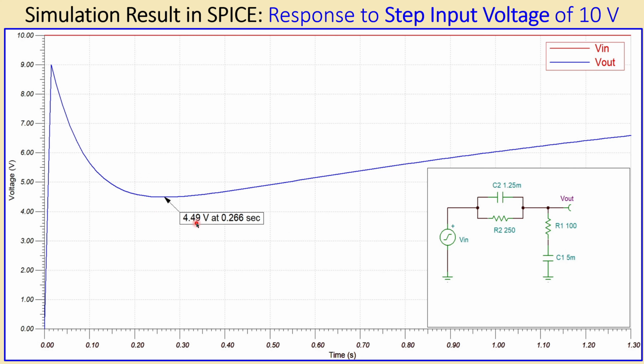You see it's 4.5 volts at approximately 0.27 seconds, which is actually also what we had. So this is the zoomed-in version, and using it you can confirm that this is indeed the correct result. That's also one of the important things when you do simulations: be careful with the sampling time and also other calculation methods to verify your results.